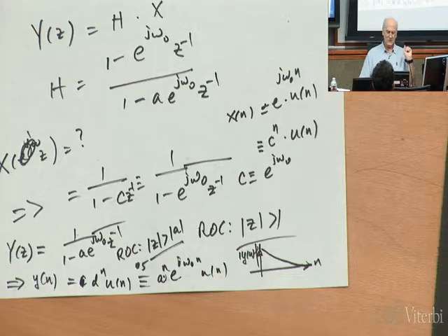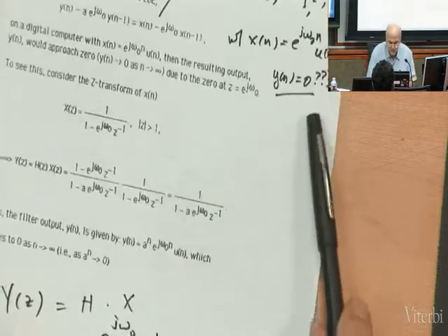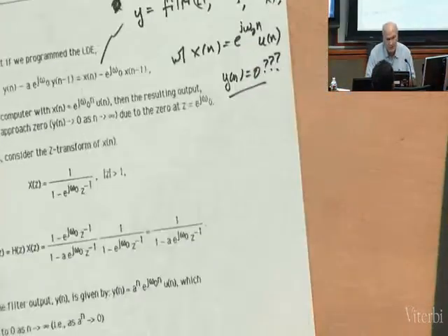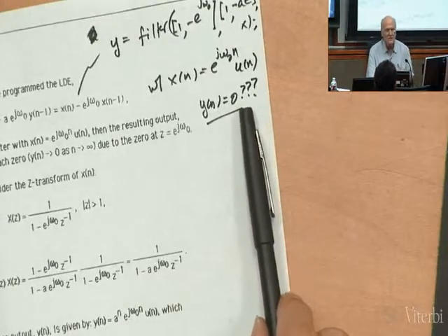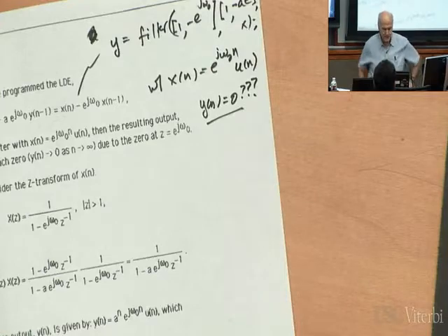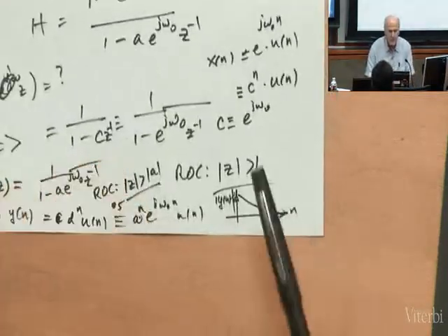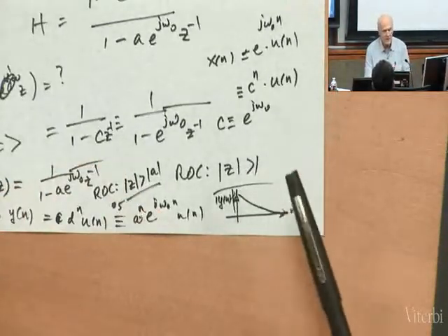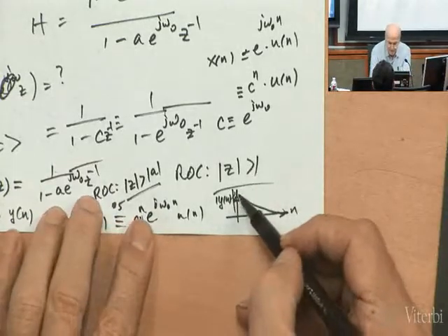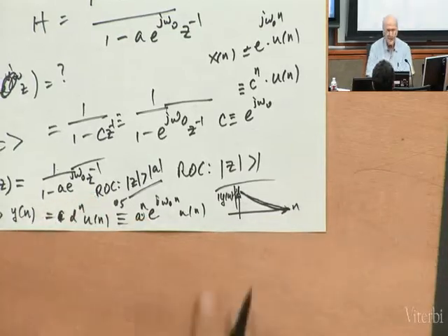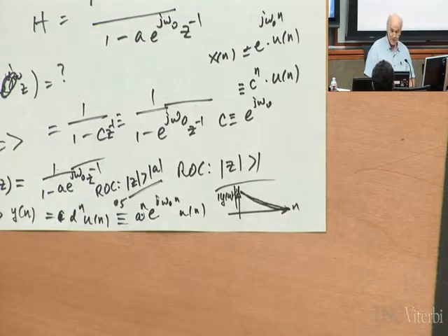So to answer your question, even though I put a frequency right at the notch frequency, does it notch it out for all time? The answer is no, it doesn't. It takes a while. It will notch it out. Ultimately, it'll get rid of it. The filter will get rid of that sine wave, but it takes time. Now, the next question is, how long does it take?